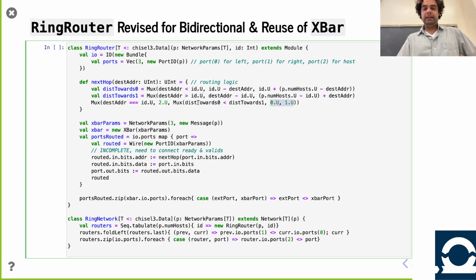So you can see that this is really kind of a pretty intimate blending of Scala and Chisel, where this is Chisel, right? This is a mux. These are working on UInts. This is going to be hardware and design. There's going to be a mux, there's going to be a comparator, there's going to be a subtract, all that good business.